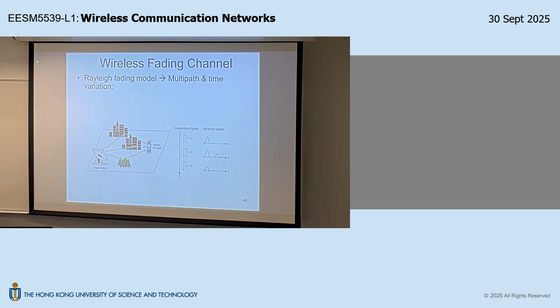So in communication, this is more like a 3D version. So imagine you have a transmitter over there, a Wi-Fi transmitter, and let's focus on this room, right? So that transmitter, if I'm the receiver, when I'm standing here, I will receive multipath from that transmitter to my location, right? Maybe the line of sight, and then reflection from this wall, reflection from that wall, right? So what I receive, the receive power, will be a superposition of all this together, right? So this dark fringe, bright fringe you imagine, spatially, you will also have dark fringe and bright fringe, or dark spots and bright spots over the space.